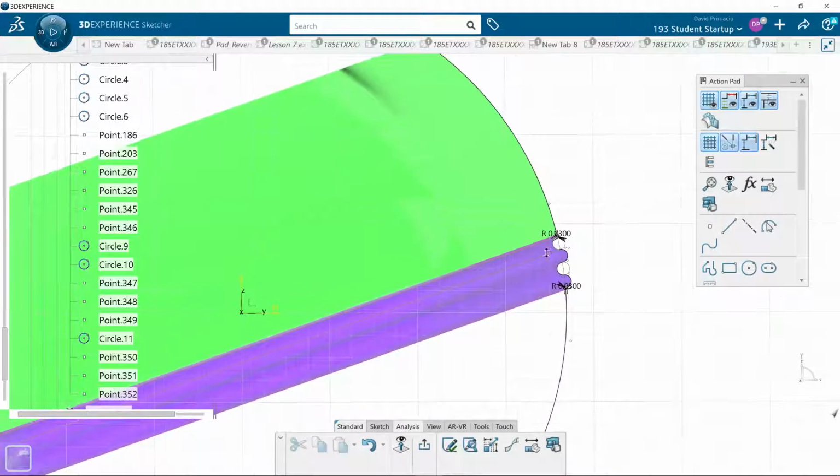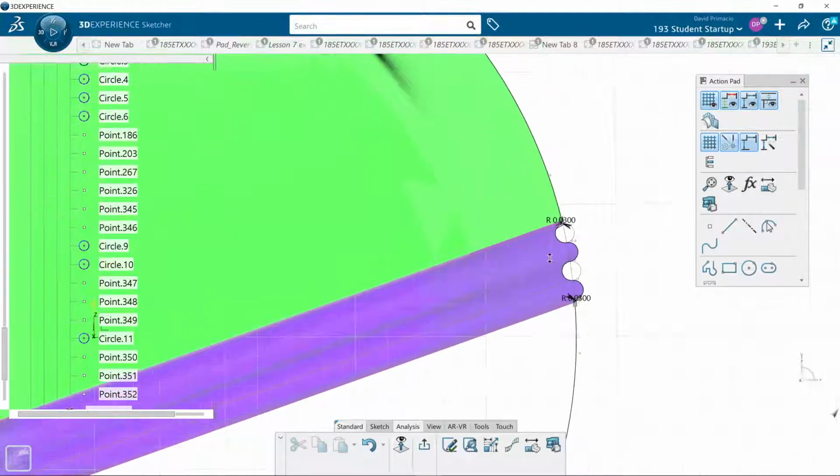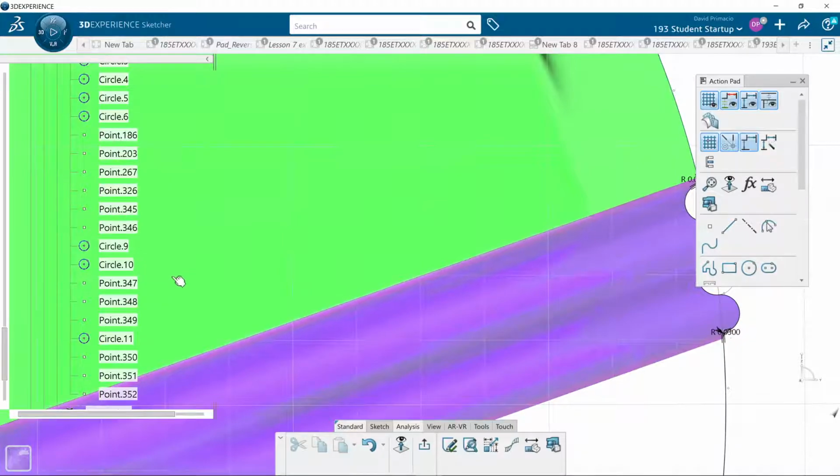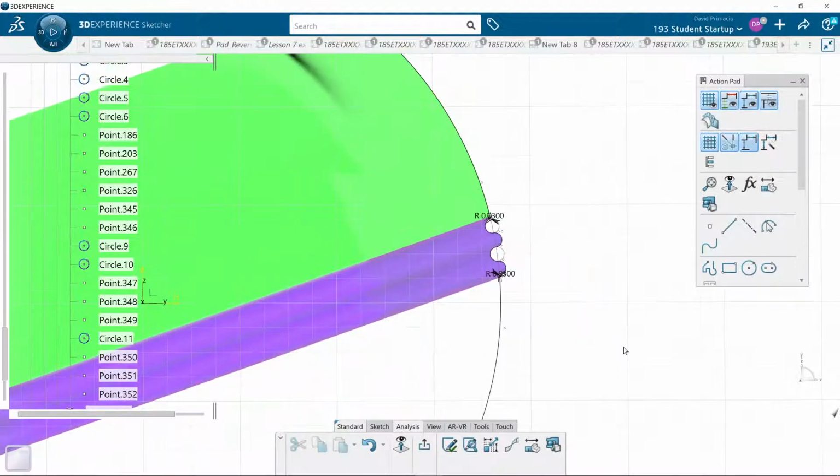And what the problem is, it's fine if it were like way over here and way down there, it would just kind of smooth itself out. But the points that they give you, they give you 150 points along a curve. All the points are really close. So all it takes is one point being down here and one point being up here, and the spline's trying to hit those points. And they would use a feature called spline, which would force it to go through a point instead of using arc comp smooth to generate the smoothest possible curve to find the median of all the points. That was one of our biggest issues when we'd have to work with the surfaces.